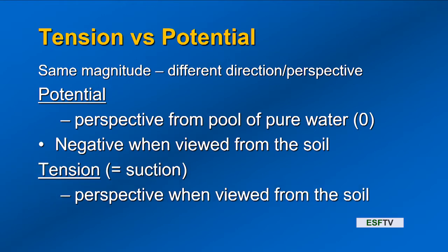It's a negative potential where we actually lose, it takes more energy to hold that in the soil. But if we think about that from the soil's perspective and turn that around, instead of looking at it from the perspective of pure water, we can think about the soil doing the work, the soil exerting a suction. And so from this perspective, we think about a positive number. The soil is exerting this positive holding power. And so it's the same magnitude, but now we have positive numbers instead of negative numbers. And that's the big difference. It's all about perspective, where the reference point is. Okay.